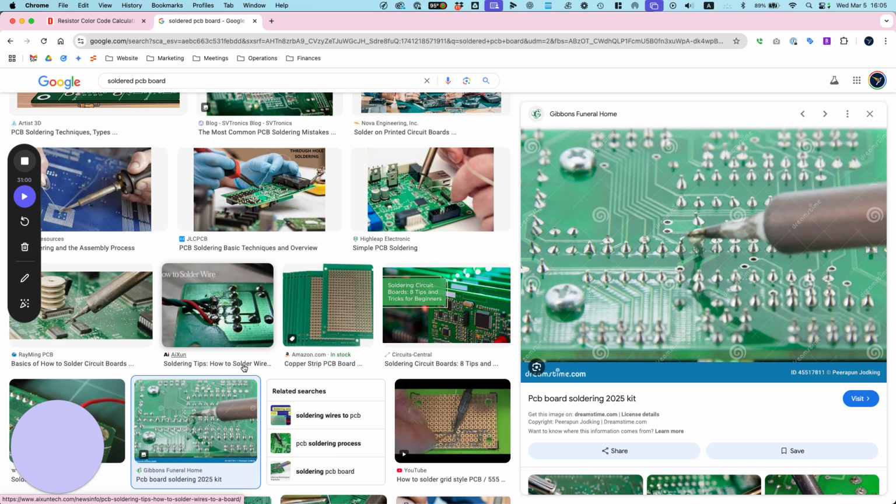On the Spires, those batteries are like $100 each, I think. So those are all dead. All those batteries are dead. If you can revive it, that'll be great, right? What happens is this has software built in where if you drop below a certain voltage, it says stop, I'm never going to let you use it again. And it's for a good reason, actually. For us to revive it, you still have to be cautious because the chemistry has changed on the inside. So DJI has put the software stop to prevent any potential issues down the line.